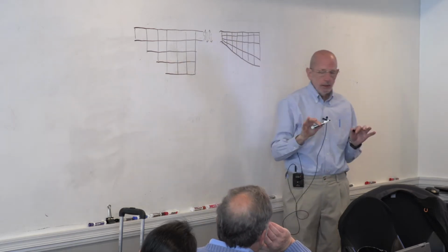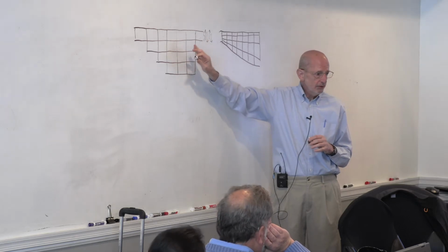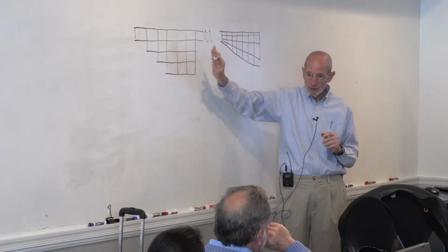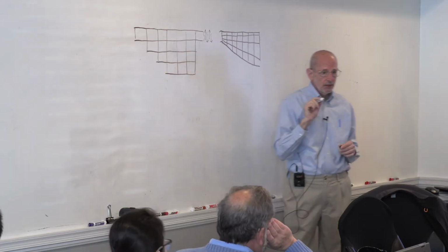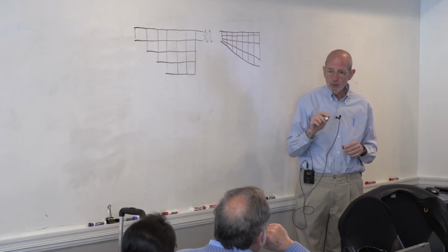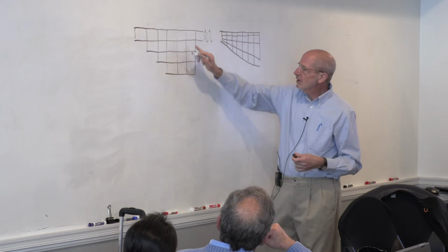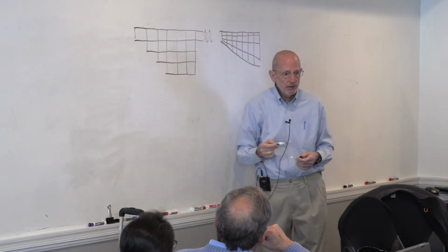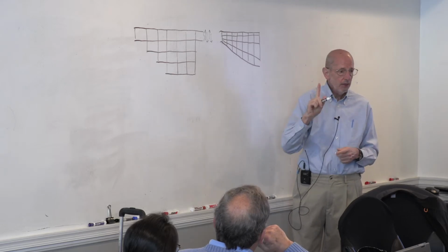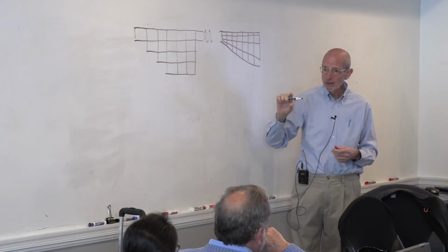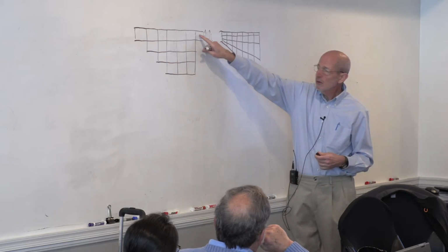So the way tide is taken care of is we change the thickness of only the surface layer. Only. These other cells, the subsurface cells, do not change thickness. And that's why it wasn't apparent here, or maybe it's confusing, but that's why for these subsurface cells, you only have to read the geometry, for example, the cross-sectional areas, one time, because they never change. The thickness never changes. This is the only one that changes.